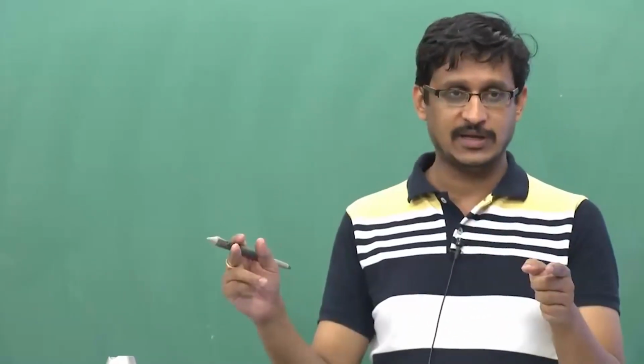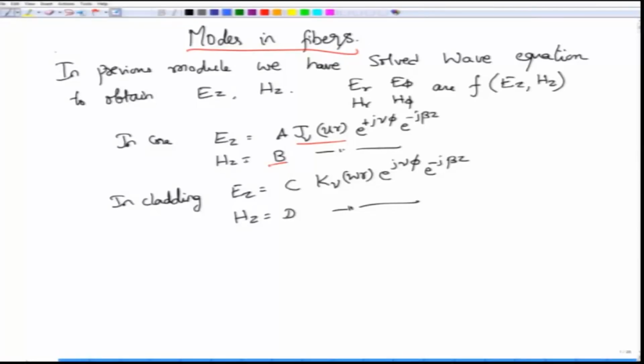This is of course pictorially, but what you actually are going to do is to set up a set of equations which tell you that Ez1, which is the electric field in the core region at R equal to A, which is the core and the cladding interface, must be equal to Ez2 at R equal to A. So, inside the core, assuming that we are looking at J0 type of a solution, this is how you would start.